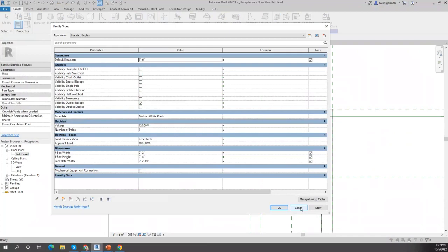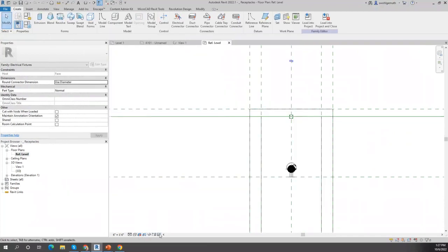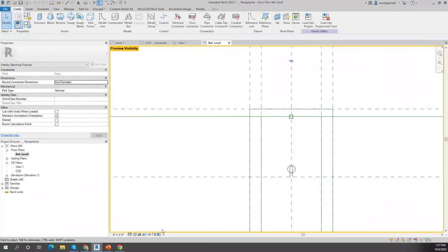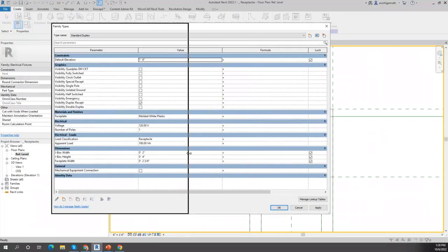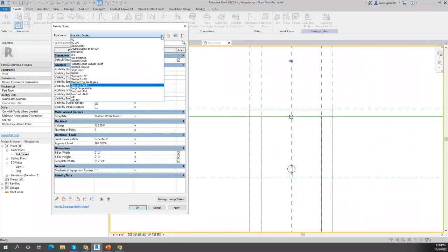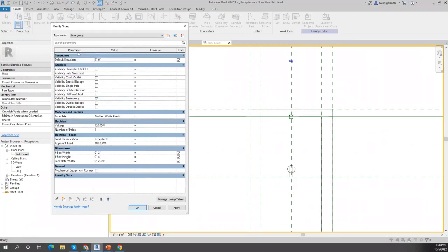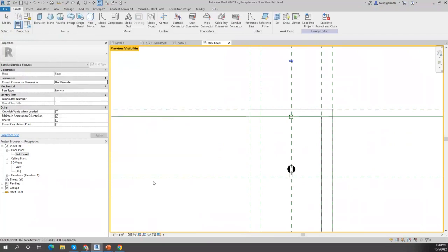It's a yes-no parameter, right? Down here in the family editor, you can turn the visibility on. And then from whatever type, let me minimize so that you can see. If I change this to my emergency and click apply, there I see the different graphics. So it's just a family with a lot of nested families, annotation symbols nested onto them.